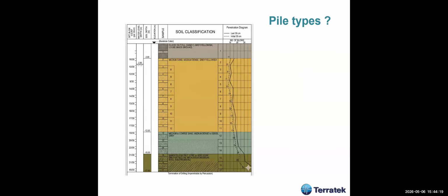And here is a quiz, but I'm going to do it together. In the quiz that you may have received, you may have other examples. What kind of pile types for medium loads or building loads would I design in such a profile? Definitely, I would go to CFA, continuous flight auger piles. And why? Cheaper than driven. I would not use driven piles in a project like this.